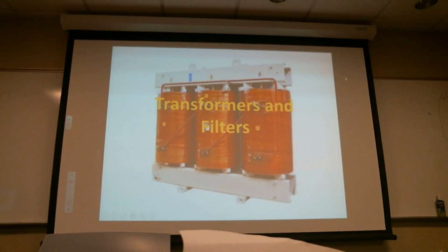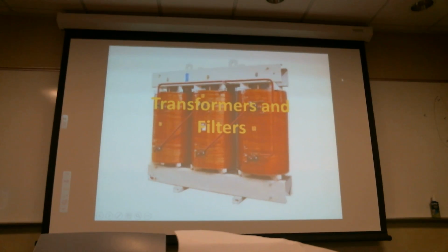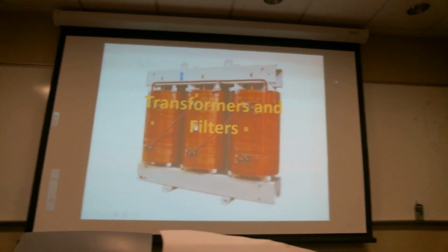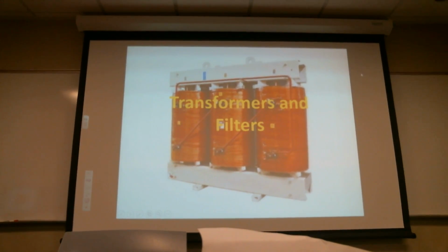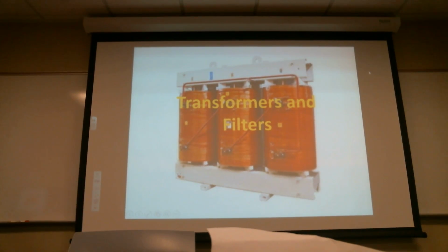But for the most part, transformers are an AC device, and in fact, the big advantage of AC is the fact that transformers allow you to transform voltage and current with each other. So that the net exchange of power remains the same, but you can raise the current and lower the voltage, or raise the voltage and lower the current.